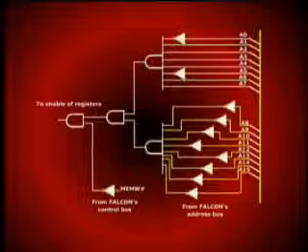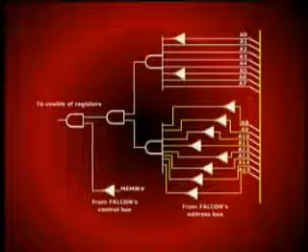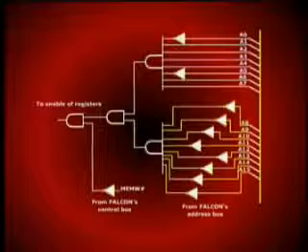The upper AND gate takes from A0 to A7, and A0 and A5, A6 are inverted, others are not inverted, meaning that the address would correspond to DE. The lower AND gate takes the input address lines from A8 up to A15, and all of these are inverted since the corresponding higher byte is 0, 0.